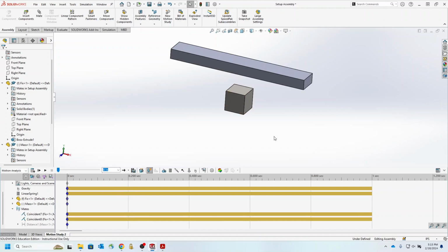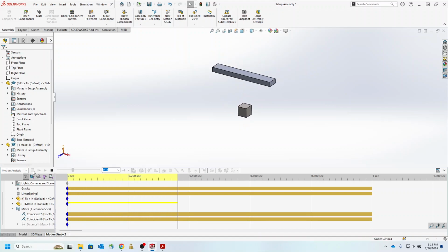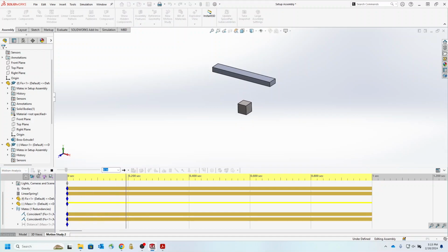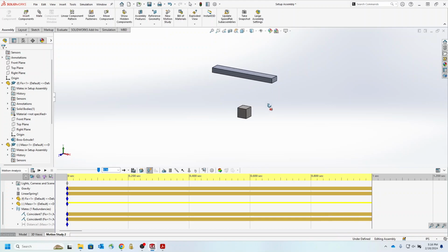And then the first thing is to find the equilibrium length. Essentially, we have to let it simulate and see where it will stay. I'm going to run it until 1 second, which should be enough. If I simulate, it's going to go here and stay at the proper length. In order to find the equilibrium spring length, you know that the spring length is something between here and here. So all I have to do is graph the displacement between here and here.